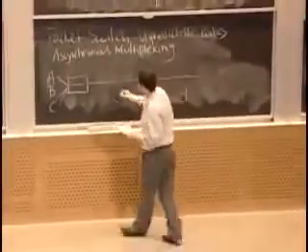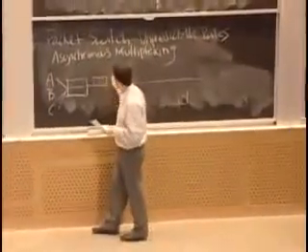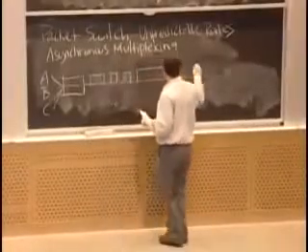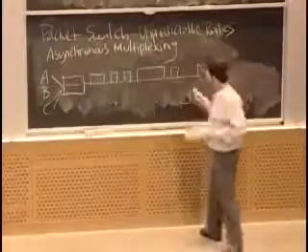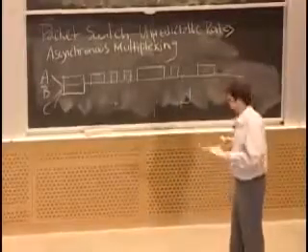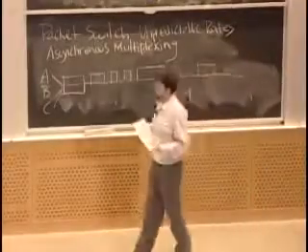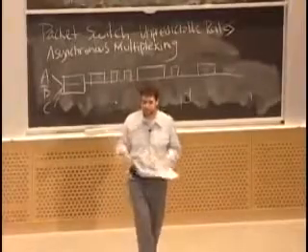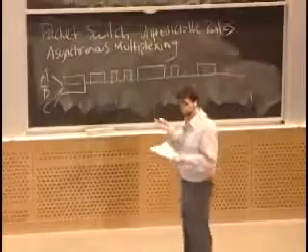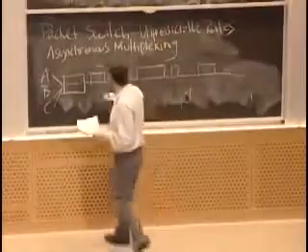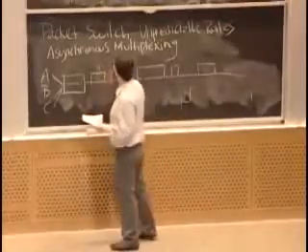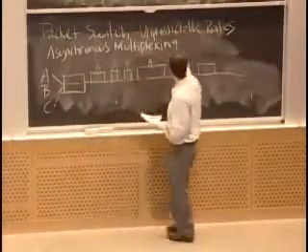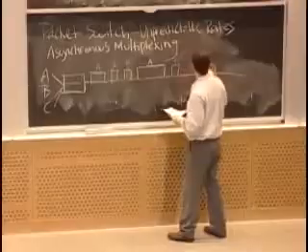If you look at the traffic being transmitted on this wire, what you'll see is that it's not necessarily going to have the same regular pattern that we had before. The idea is that any node is allowed to try and start talking on this wire at any time that it wants. That's why it's called asynchronous. It's not timed. There are no regular slots when nodes are required to transmit. So this might be traffic for A, this might be traffic for A, this might be traffic for B, A, and C.